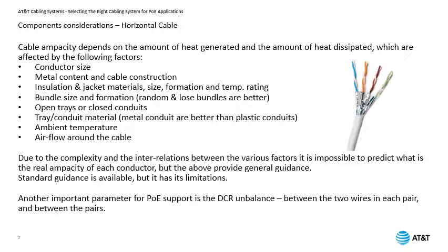Then we have factors related to the installation: the bundle size and the bundle formation, open tray or closed conduit, the tray itself, the tray material, whether it is metal or plastic, the ambient temperature and airflow around the cable.